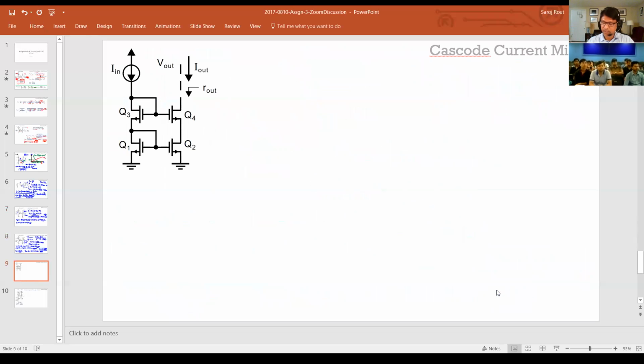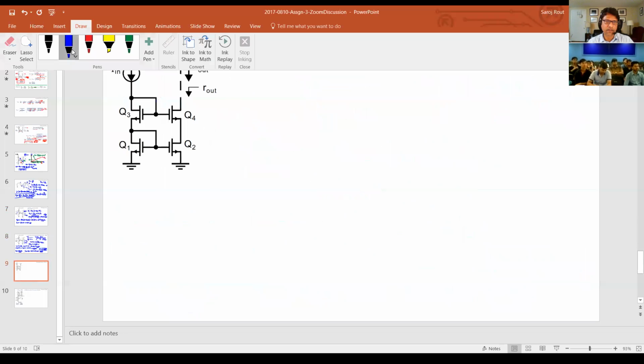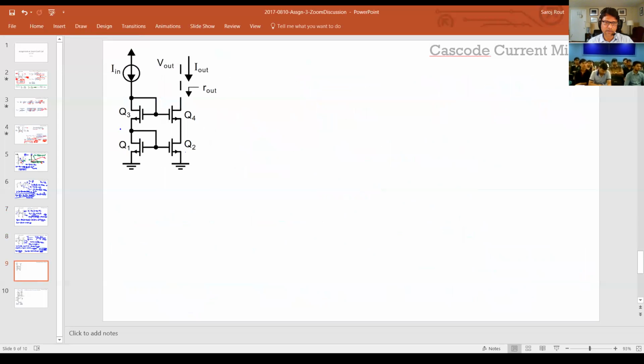So what we do is, instead of actually using a physical resistor here, we actually use another current mirror. So you can see this bottom part is actually another current mirror here. So it's actually two current mirrors stacked on top of each other. So this is nothing but, if you see the previous example, the degenerated current source, you can approximate this as that equivalent RS, right?